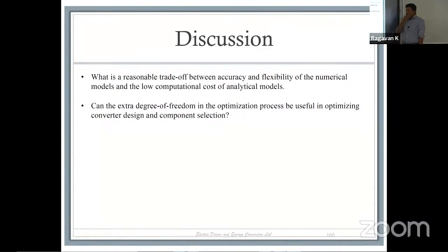There will be some coefficient called the coefficient of prognosis. If that value is above 0.9, that will be a reliable result when we are reading from a metamodel. But if it is less than 0.9, that may not be reliable. My question is, how will you make sure that whatever the intermediate results are, they are reliable?